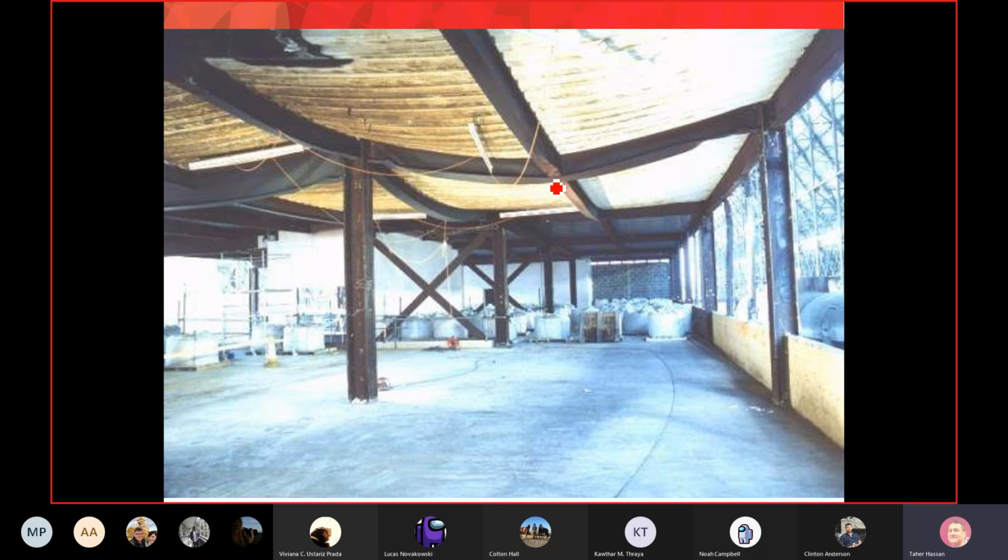And that's why part of our design, and that's something you will see next year, is to limit the amount of deflection. So we design for strength, making sure that our beam will not fail under the load, and also that under loads, we get an acceptable amount of deformation. And this picture also shows you how the beam bends. Look at this beam. The bottom fibers are in tension and the top fibers are in compression.